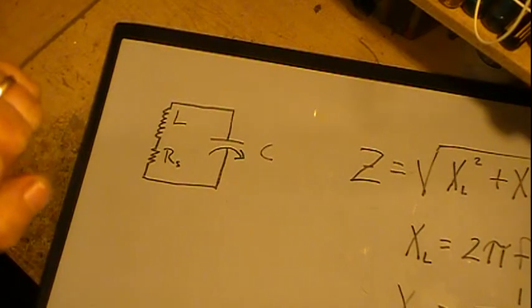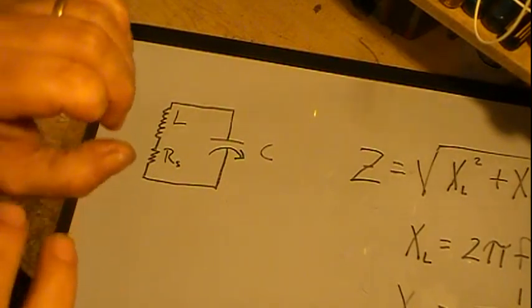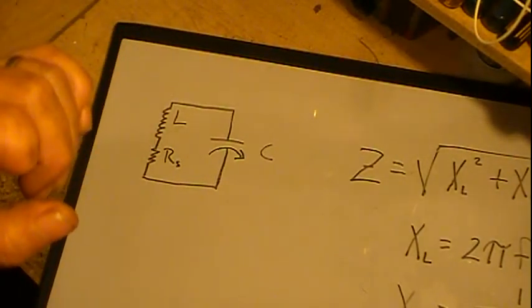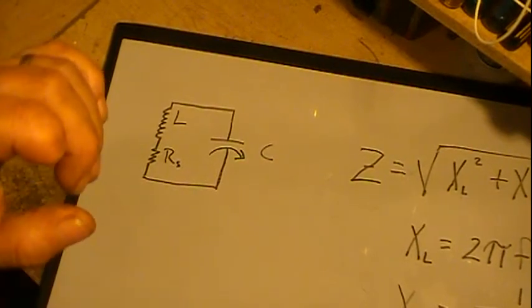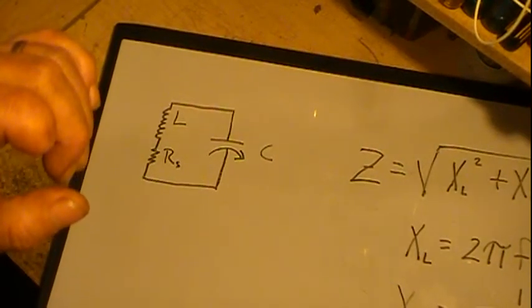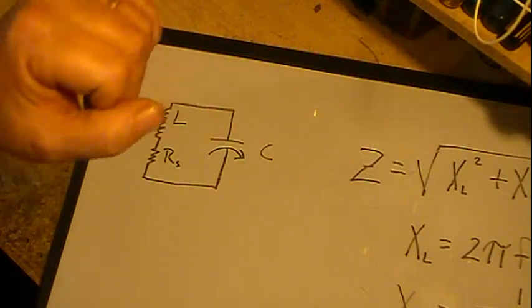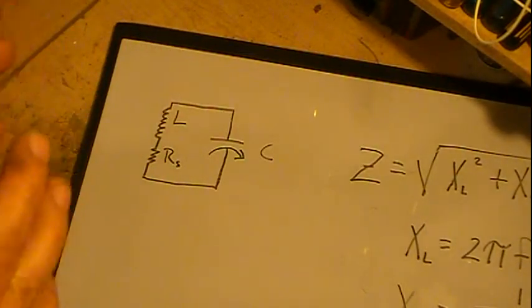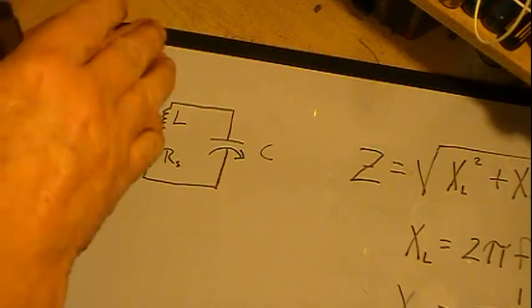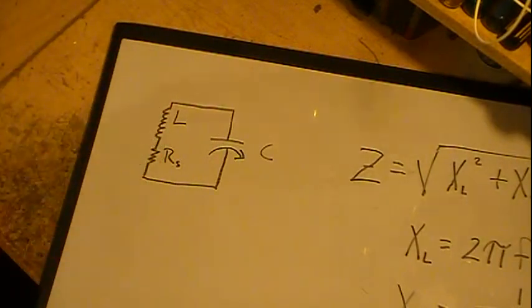You heat the wire slightly to make it a little more malleable, and you use lubrication and everything else, but you just keep pulling it through dies that are smaller and smaller until you get to the size that you want.